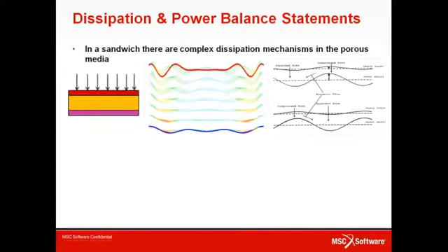Many industrial applications where the reduction of acoustic transmission is required involve what we call sandwich structures. In those applications, one typically tries to reduce the noise transmitted from one side of a metal structure to the other side. And this is done by adding a layer of porous medium with on top of it a layer of septum. Such septum has typically a high mass and a low stiffness. And thanks to this, the vibration patterns in terms of wavelength and amplitude of the metal sheet and of the heavy layer are completely decoupled from each other. And because of that, a strong dissipation can occur in between, that is, in the porous layer.